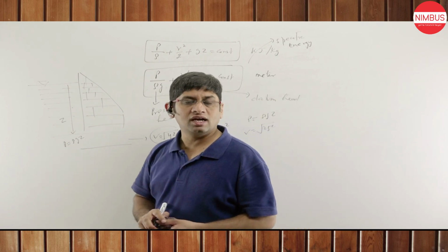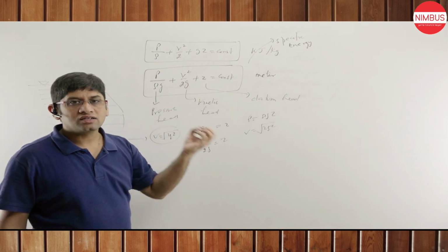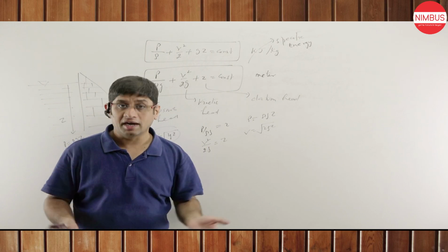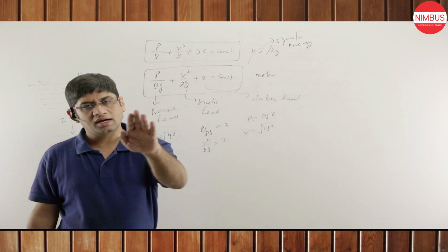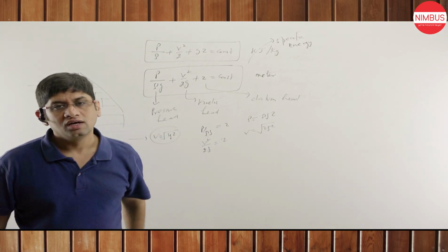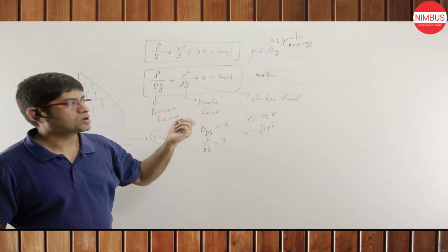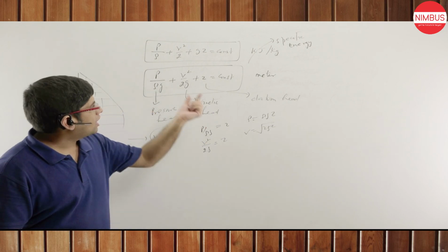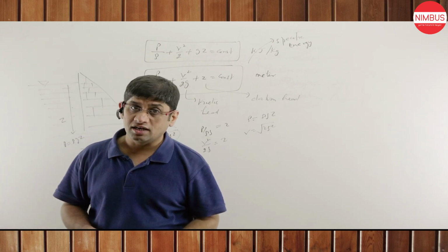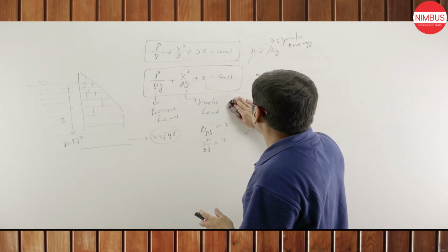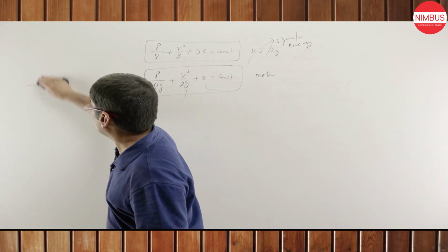So why do you write Bernoulli equation in terms of head? Because sir, in the beginning fluid has energy, or fluid has power in the form of head. When we store that particular fluid, from that stored fluid I can calculate directly pressure of the fluid, I can directly calculate the velocity of the fluid flow in terms of head. So these terms directly can be used to calculate velocity at the exit of the nozzle and pressure at the bottom of the reservoir, if I know that the fluid is stored up to z depth in the reservoir. So is the question clear why you write Bernoulli equation in this particular form? That is the question he is going to ask you.